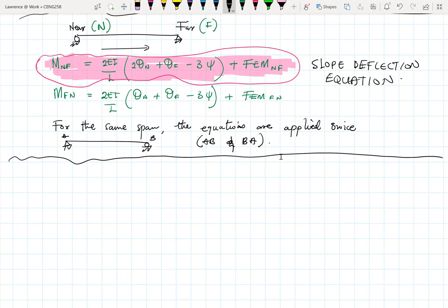There are a few steps if you have to solve a problem. The first thing you need to do is identify and determine the fixed end moments, and I don't need you to do that from first principles because books have that already done for us. Hibbeler, for example, has it on the first page. I think I have that also on the V School.